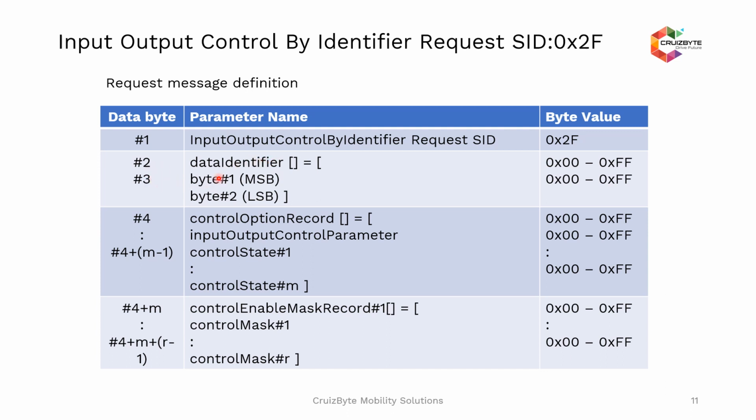As we discussed previously, a data identifier could be an array of signals packed into one DID value, which is also called a data identifier, or an individual component. Say for example, engine speed alone can be a data identifier, and these DIDs are listed previously when we develop the ECU. It was part of your software development.